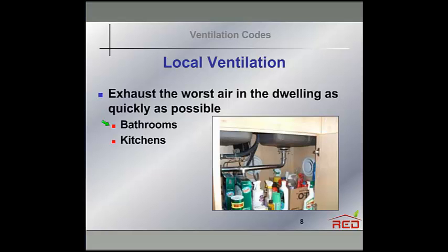Those are not considered hazardous, but within the ASHRAE committee, we've been back and forth about requiring the ventilation of half baths where there is no shower or bathtub. At this time, the standard does not require that. It only requires local ventilation in full bathrooms. A full bathroom is one with a bathtub, a bathtub-shower combination, a shower, or a spa.